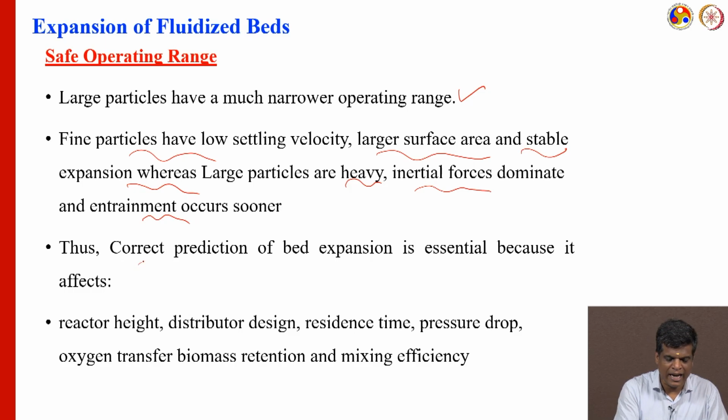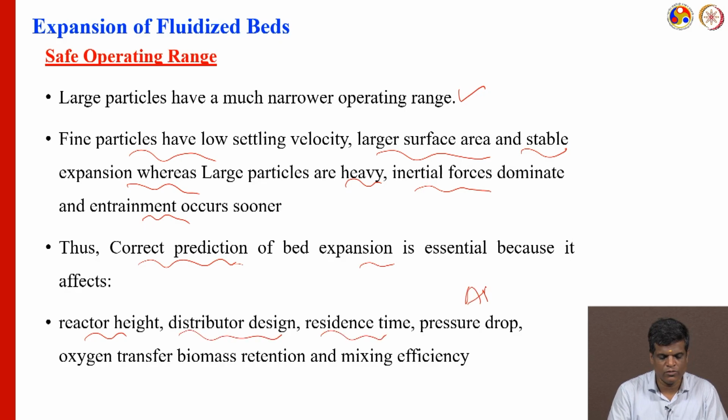A correct prediction of bed expansion is essential. It affects the reactor height, the distributor design, residence time, pressure drop, oxygen transfer, biomass retention and mixing efficiency. Otherwise it will affect all the parameters or variables mentioned. So, we have to study the prediction of expansion.